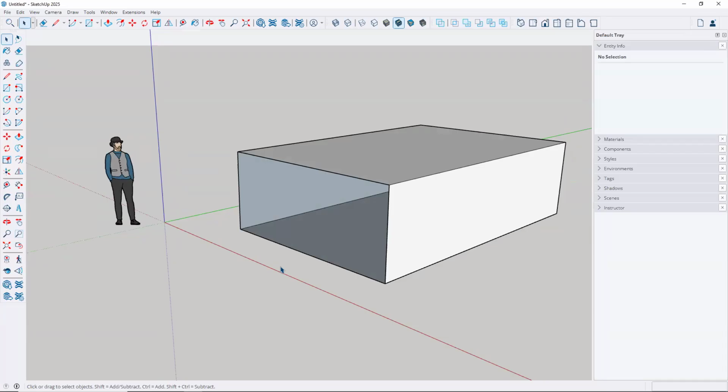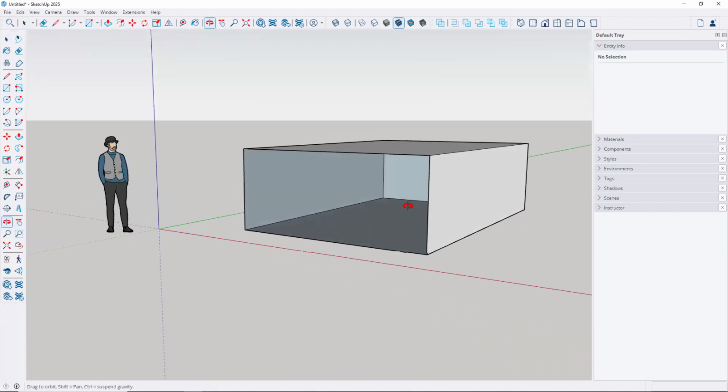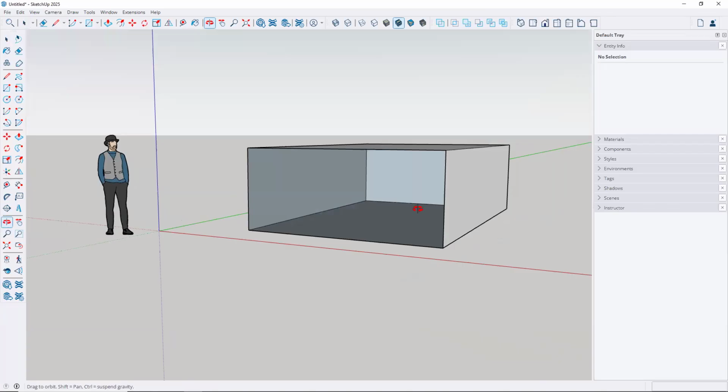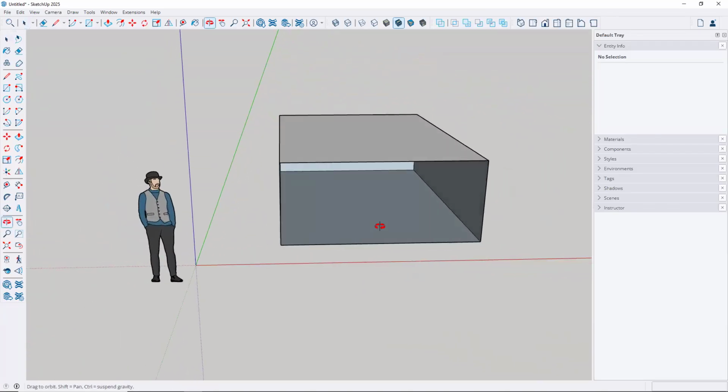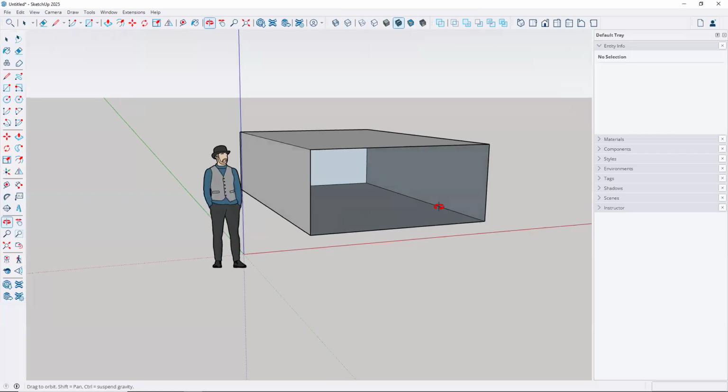It's like taking cards or taking paper and just putting 6 sheets of paper together. The edges are touching and hollow on the inside, but from the outside, it looks like it's a solid object. That's just how SketchUp works. And then the other thing I did here, the reason I took that face away is because I want you to see that on the inside, there's a color to that surface, and it's a cool gray color.